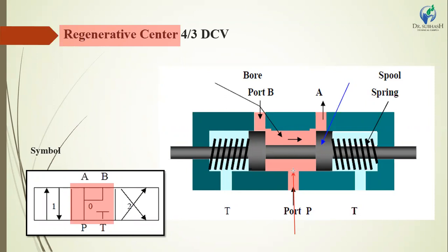The direction control valve opens both point A and point B, not sequentially but directly. The oil is equally pressurized and passes to point A and point B. Both points are in an operating condition. Either may be an input or an output. The flow direction is not fixed.